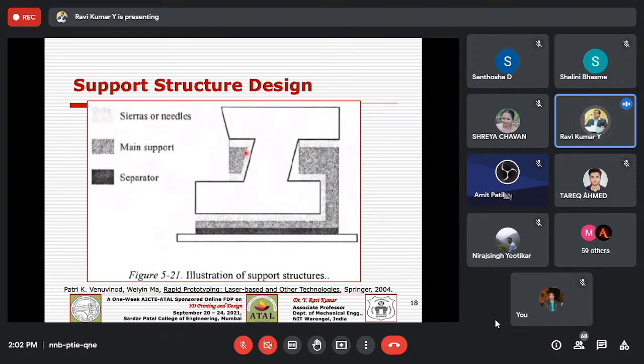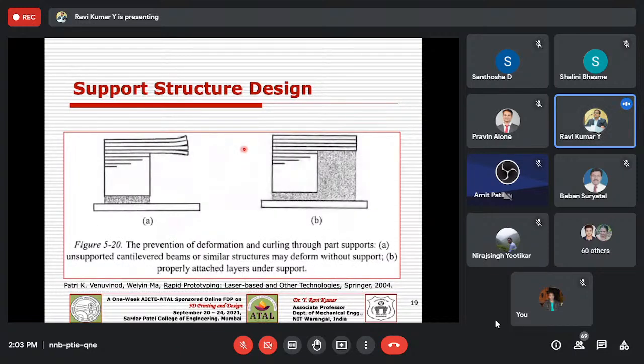But the support structure has its own function, to be the anchor, or to support the overhang portions which we need to give a support. Or it can even be responsible for heat transfer. We never outrightly eliminate the support. Sometimes it is very much needed, but you try to minimize it as much as possible. Then your design for additive manufacturing is going to talk about that.